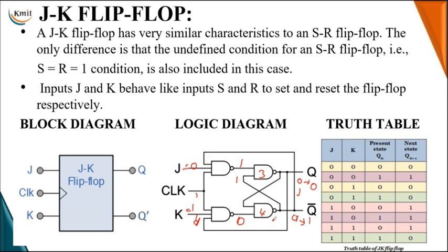So 1 is transferred as your input. If all the inputs are 1, the second NAND gate output will generate the 0 output. The fourth NAND gate output will transfer the logical 1, and when this is transferred, 1 is shifted to 0. If both inputs are 1, the third NAND gate output becomes 0. So present state 0 continues with the same state. If present state is 1, then it is reset. So K input is exactly equal to reset input, hence it resets your flip flop or loads the logical 0.